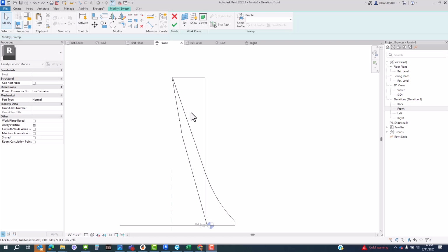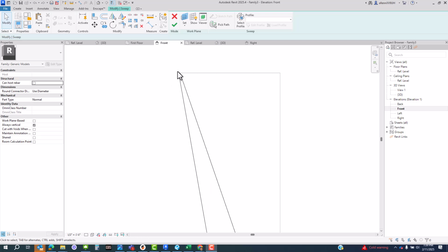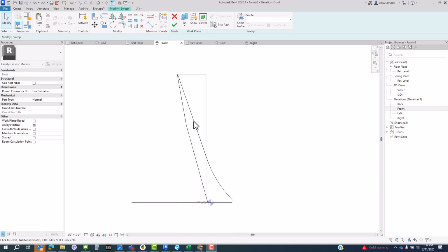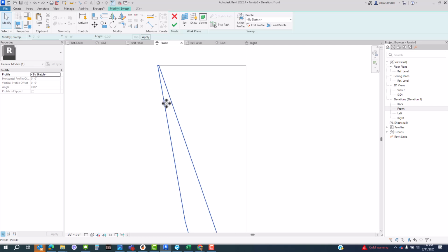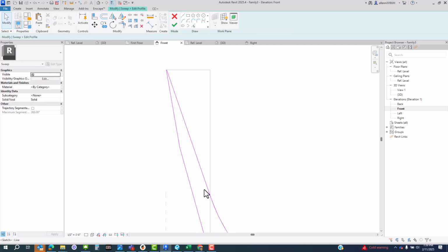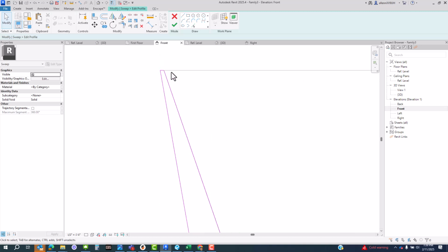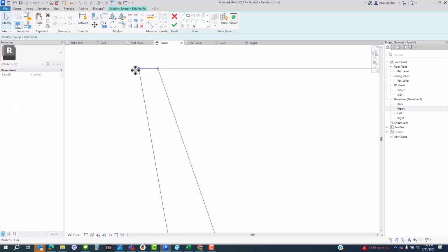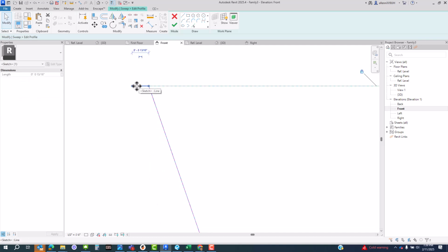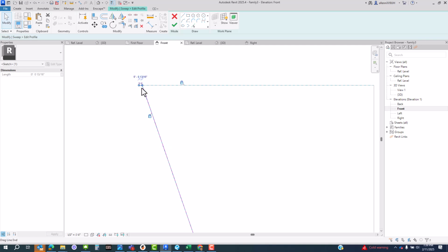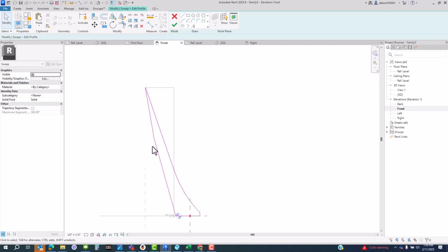Okay, I fixed it. It didn't really like that at the very top, if you recall, that shape went right to the center of the whole thing. In other words, this outline lined up with this center reference plane. They don't touch anymore because I simply double-clicked on the shape and I modified it. And up here, I just took these two lines and I just pulled this in. Actually, that's not true. I deleted out the line that was here. I pulled this one over to the right, and then I just started drawing new lines to create the back side of this, the underside of this roof.